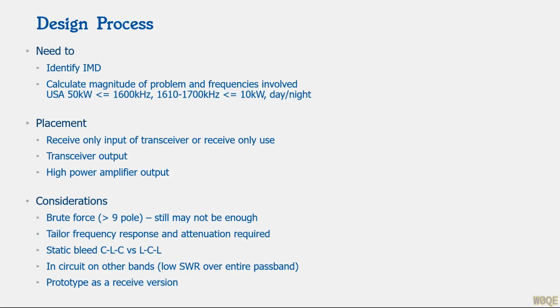And again, the problem here is one of power and one of location. If you happen to be unfortunately located close to a radio station or line of sight to them, you're more likely to have a problem. Now, different receivers have different sensitivities to intermodulation distortion, but all radios exhibit the problem. No matter what the radio is, you can have a strong enough signal that the radio is driven into nonlinearities.